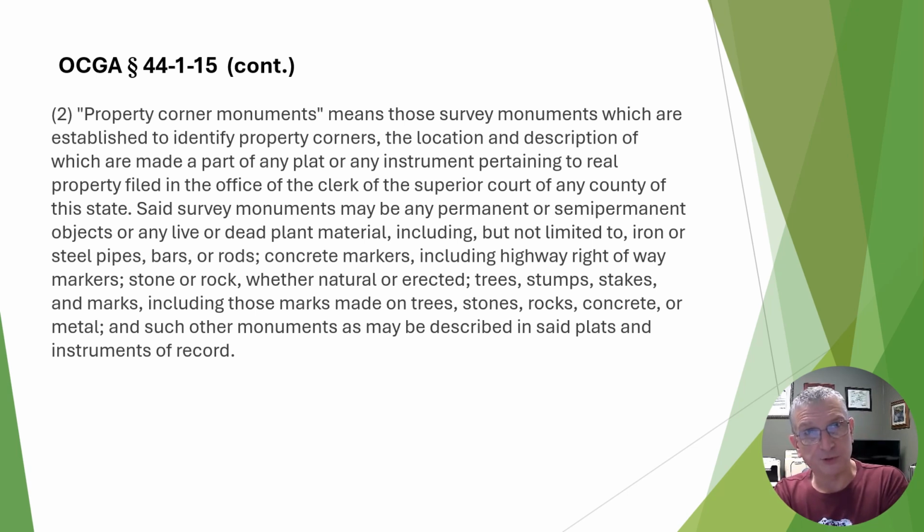But you could also come back and say, but that's a marked tree, marking a property line. I could always come back and say it's not marked as being on the line. It's just saying the line is over there somewhere. So you kind of get into a little fussy subjective argument there. But the law itself goes down and says that it might even include trees, stumps, or stakes, or even marks made on trees may be protected property corner monuments under the law.